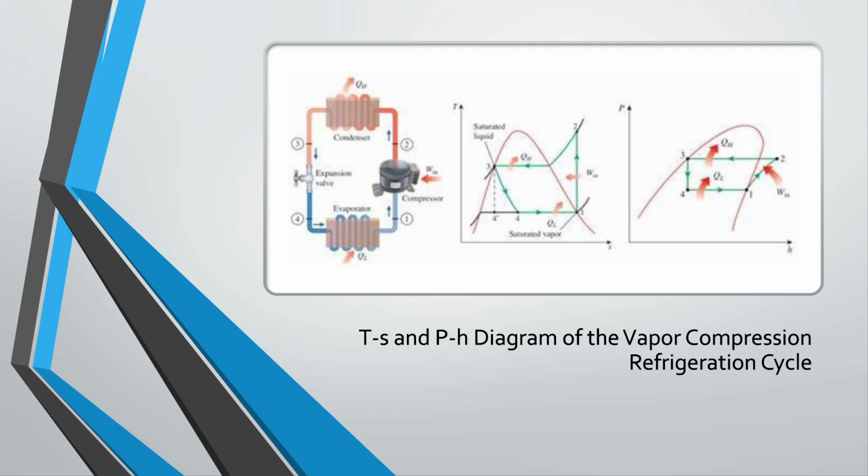When the vapor enters the compressor, we see a steep rise in pressure and enthalpy. This represents the work done by the screw compressor. In the condenser, the refrigerant rejects heat to the environment, causing enthalpy to decrease while maintaining high pressure. Finally, during expansion, the pressure drops sharply and the refrigerant returns to its starting point, ready to absorb heat again.